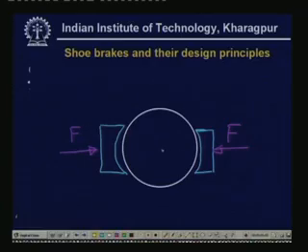Now there is no bending stress developed in the shaft containing this drum, but the friction force is developed. We can see this friction force is such that the frictional torque is now double. So, it increases the braking efficiency or braking force, and it does not introduce any undesirable bearing stress or bending stress in the shaft. So, this is normally what is done.